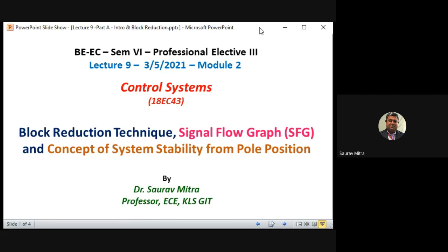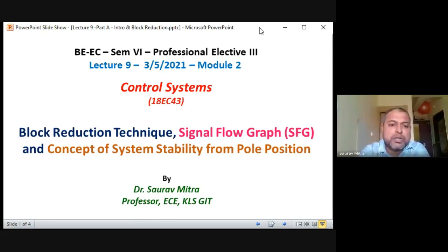Now if we solve the characteristic equation, whatever roots we find, we check what the real part of it is. It is not necessary that every time the characteristic equation will have real roots. Sometimes it might have imaginary roots. If it is a real root, no problem. We have to check whether the roots are positive or negative. If the real roots are all negative, that means all the roots lie in the left hand side of the S-plane, and the system, whose transfer function we have found, is called stable.